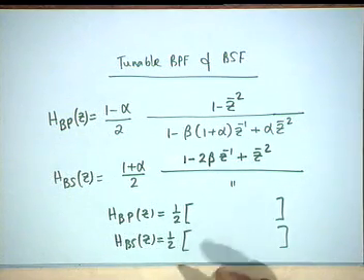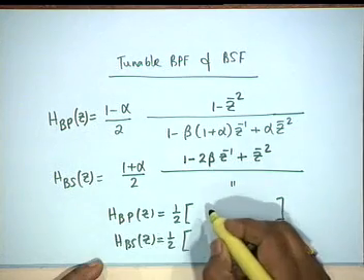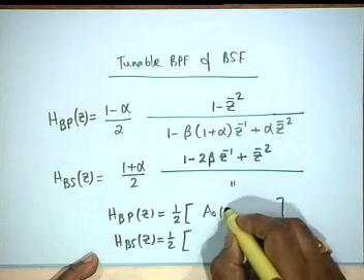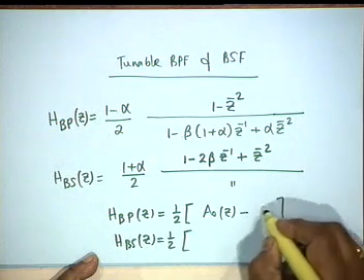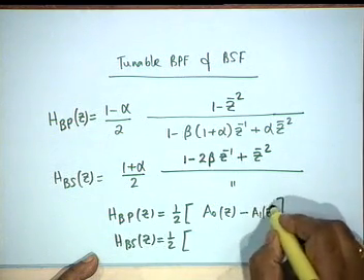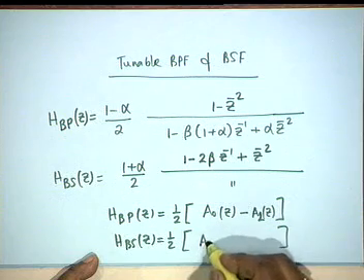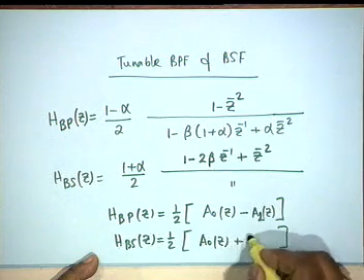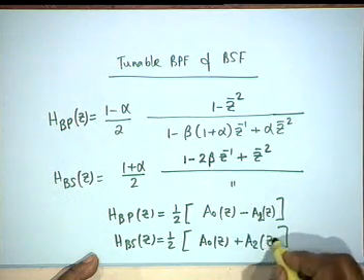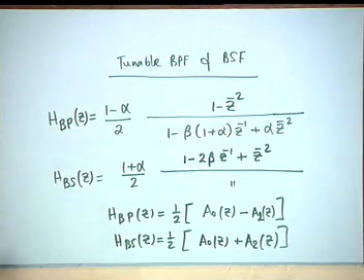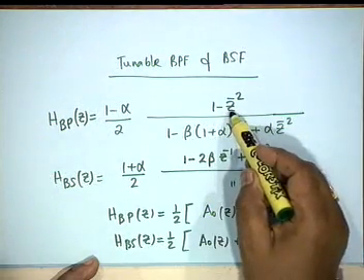But here, unlike the low pass and high pass, the band pass is the difference, A1(z) minus A2(z), whereas the band stop is the summation of the two. Does this appeal to common sense? You may not have remembered, but the way to remember it is there is a negative sign here.